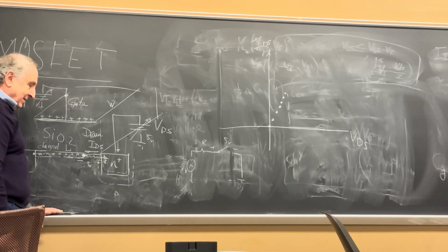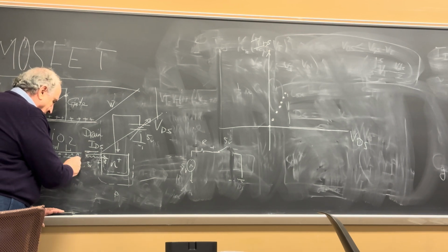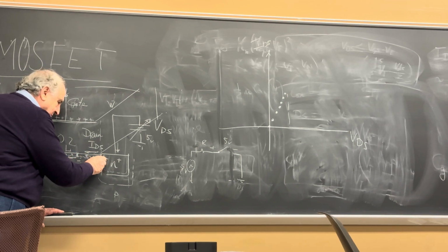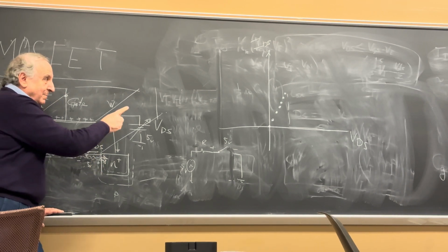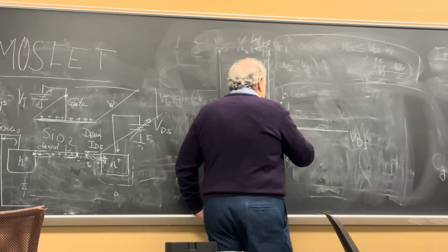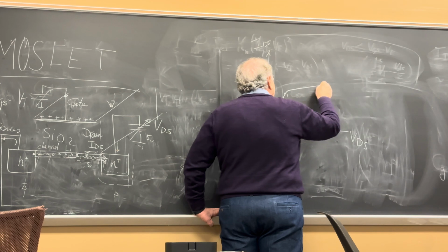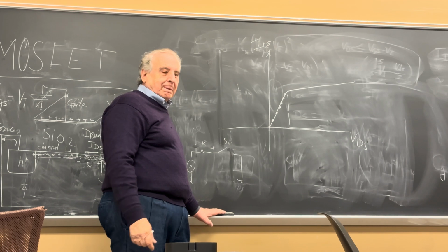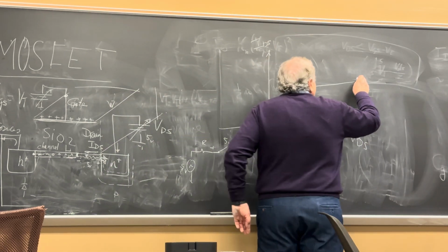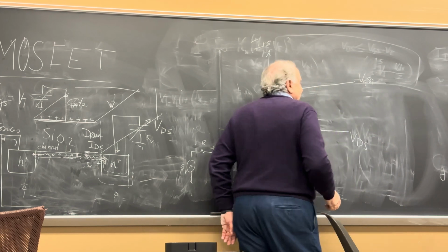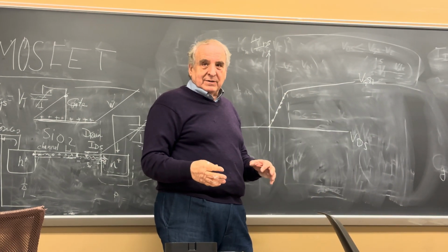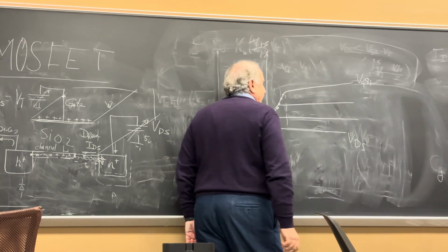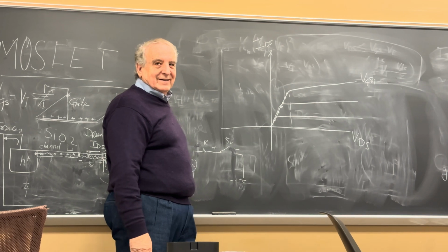Now I increase that voltage to 6 volt, here's the channel. It remains tunneling because I increased this. So what happens to the current? It levels off. It looks like that. Okay, it's leveling off. Now, this is for VGS1. For one channel, if I put another VGS, I'll get another curve. Does this look familiar? Yeah.